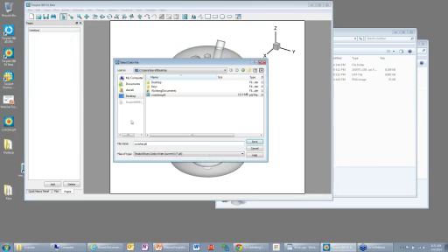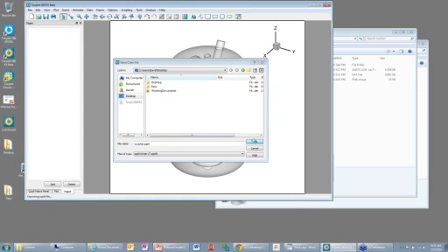Now let's write it as an SZPLT file. Notice, although this may not be obvious to all of you, maybe many of you haven't worked a lot with add-ons, but our subzone loader and writer is all done as a Tecplot add-on. So there's nothing you're seeing here that, if you were interested in writing add-ons yourself, you couldn't also do. So we've added the ability to register data exporters from 360, and I'm taking advantage of that now with our subzone loader. So I'm going to save this to the desktop also as an SZPLT file.